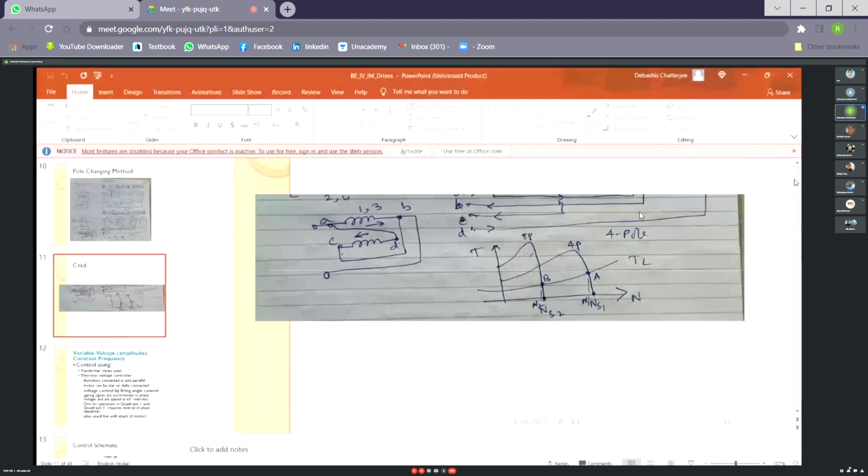But in case of slip ring machines, you need to change the rotor connection also. The rotor is a rotating body, so it will require slip rings and brushes to bring all the coils outside. Naturally the shaft extension will be too large if you have many coils, so this is not exactly feasible for slip ring type machines.